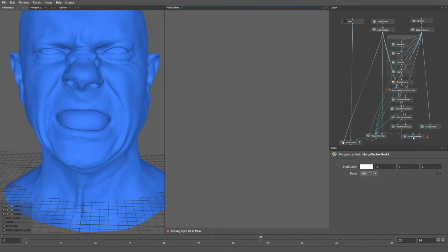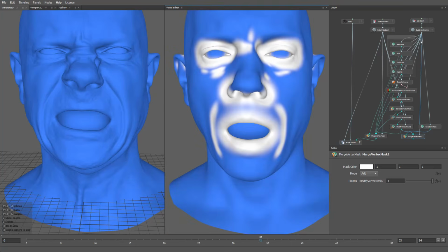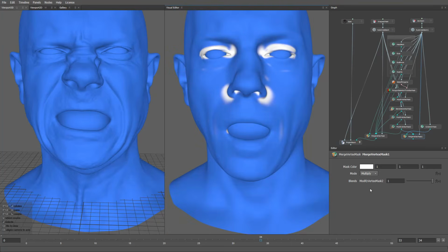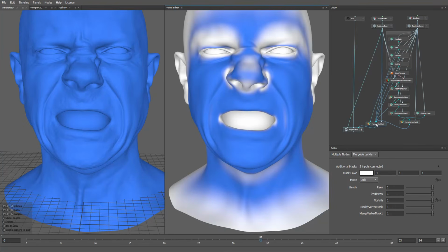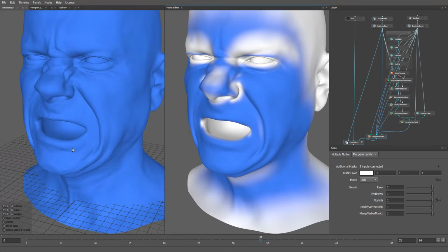Let's use Merge Vertex Mask. We'll input our constraint as the primary mask and the generate vertex as the secondary mask. Input our static geometry jaw open and choose the multiply mode. Instead of the full generate vertex mask, now use it with the new constraints. Great, here's the result. We can see the difference now. Check additional examples to confirm everything works well.